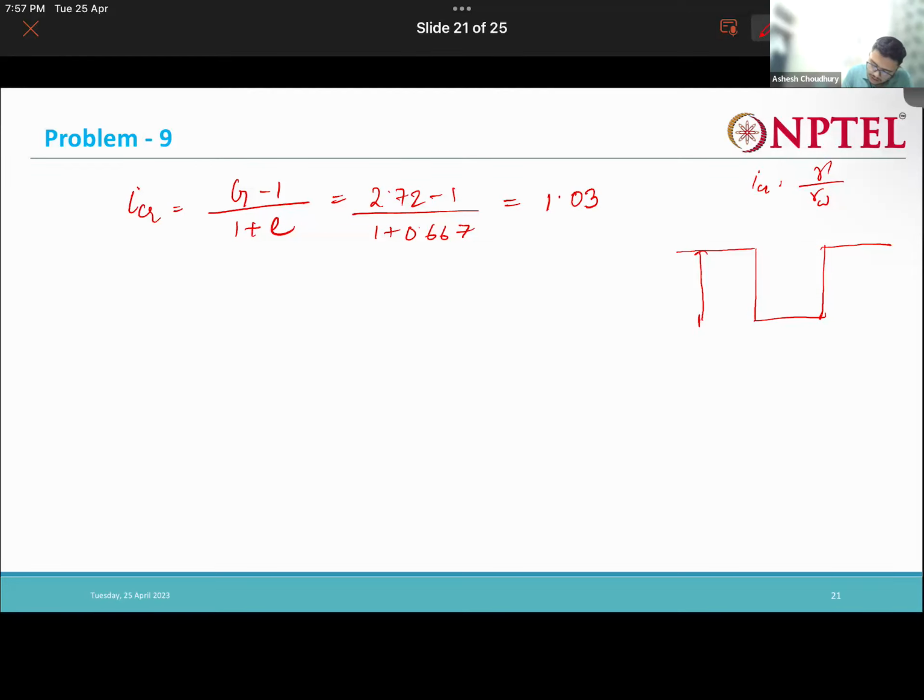Initially you have a 1 meter thick layer, and here also drainage is there. This is the drainage. Then you're introducing a very thin pervious soil layer here. This layer will also act as a drainage layer. So you're increasing the amount of drainage path, and for this reason the consolidation will get accelerated. Water from here will come here and get exited somehow, and water from this layer will also get here, flow along the drainage layer, and get exited.